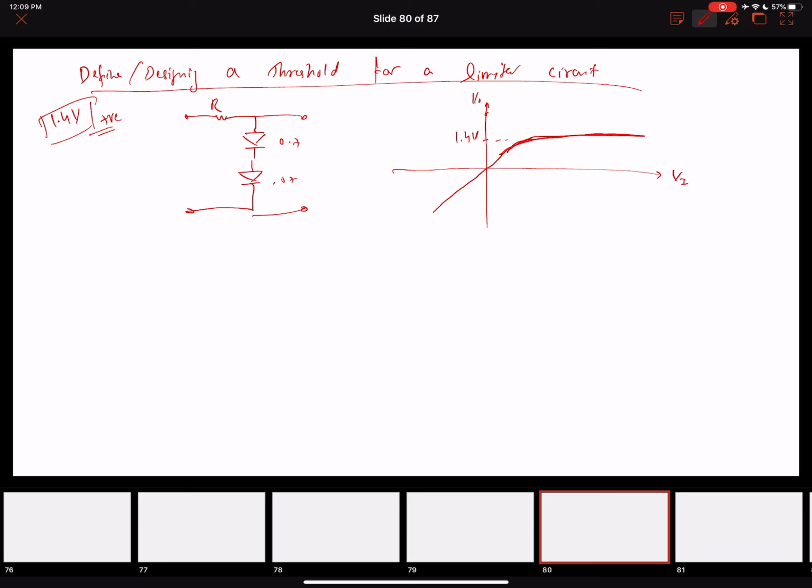What if I ask something more different? For example, again, I want a positive limiter. I want a positive single limiter, which means the diode can be connected in just one direction. And I want a positive peak limiter. This means I can connect my diodes like this. Otherwise, it would have been the other way. And then I want the threshold voltage to be, let's suppose, 4.7 volts.